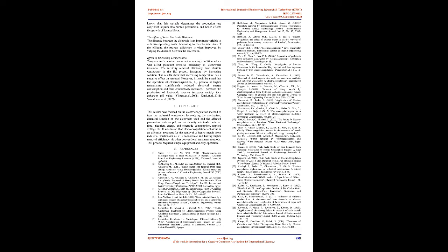Zodi et al. 2009. The EC time is an important parameter that is influential on the electrocoagulation (EC) process. Electrolysis time is of vital importance in the performance of the EC process. It is found that removal efficiency of TS, COD, and FC increases with increasing electrolysis time up to 15 minutes. Thereafter removal efficiency was observed almost constant. The removal efficiency increased with settling time.